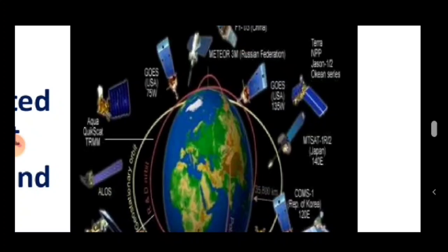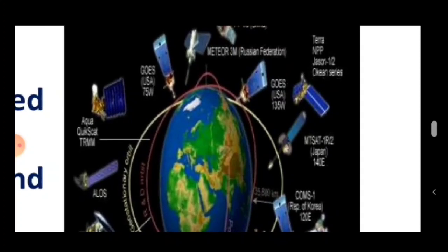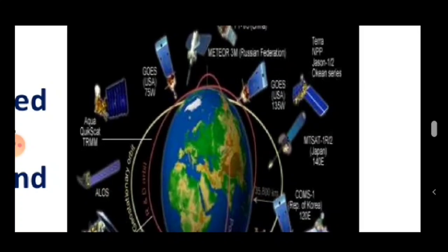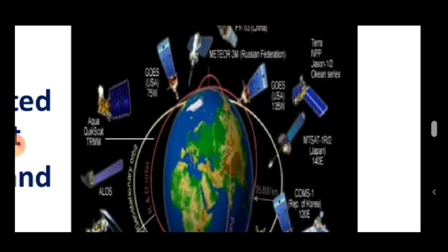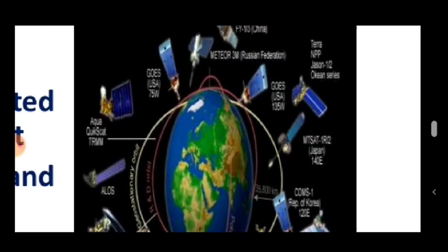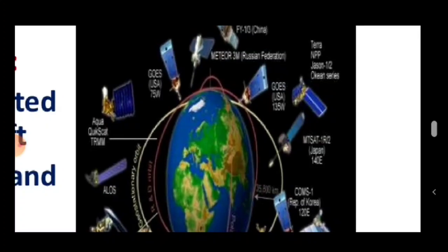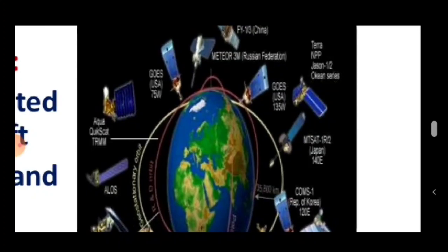It is a near polar, sun synchronized satellite system, which revisits every 16 days, at an altitude of 438 miles or 705 kilometers. Landsat 1, 2 and 3 carry multispectral scanners with 80 meter pixel resolution and record data across 4 wave bands: 3 visible channels and 1 near infrared.